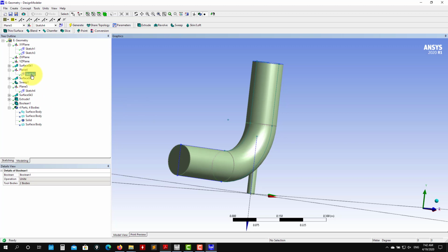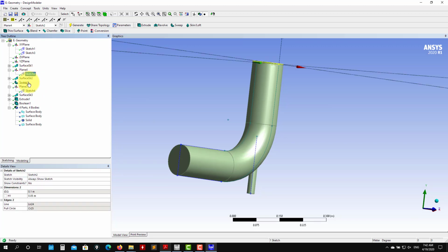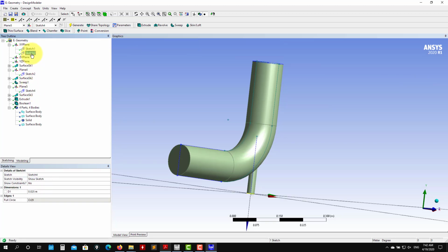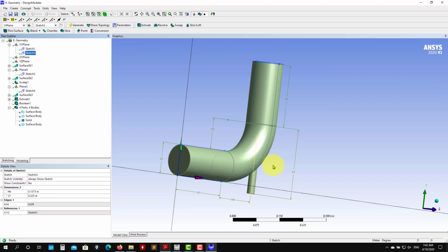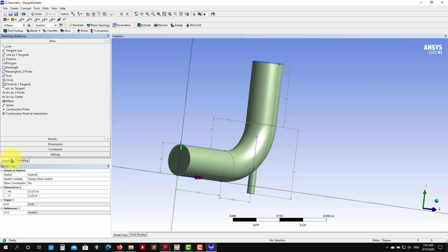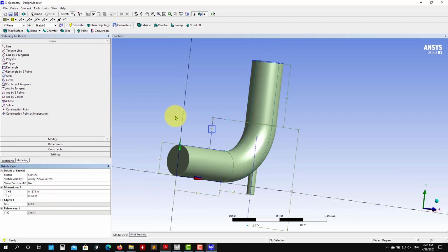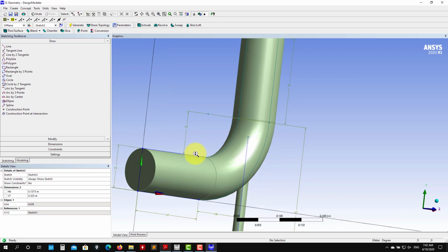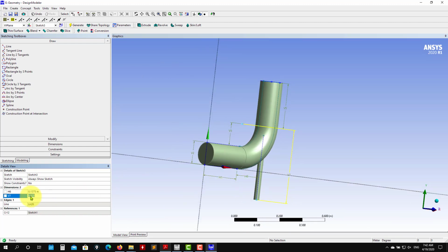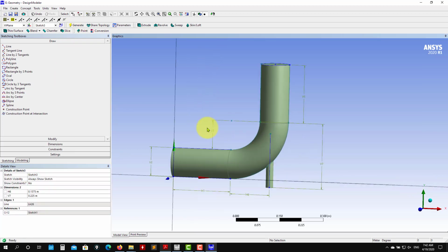So for instance, I can change, let me see, okay, that support line, for instance. So I will go and I will change B7, I will put here this value, and you press generate and see that it's updated automatically. Okay, so this is the advantage that everything is parametric. So then you can use design space exploration study, very easy.